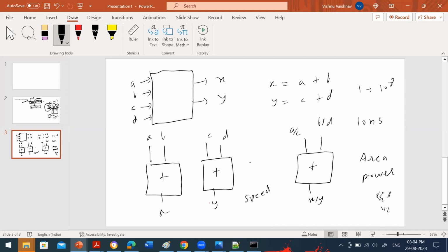And even if you take the worst scenarios, let's say some gaps in between and not getting the exact propagation delay or some tolerance, still I think you can do 10 raised to 7 operations in a second. How fast it is. So I think it's not a bad idea to go with one adder. You don't need more speed. Humans are not that speedy. Even if you feed this adder to any system, you won't get inputs at that speed. Such points we think about when we make the architecture.